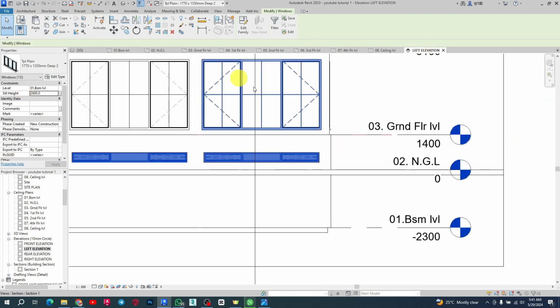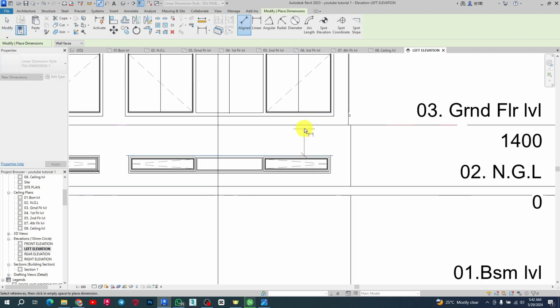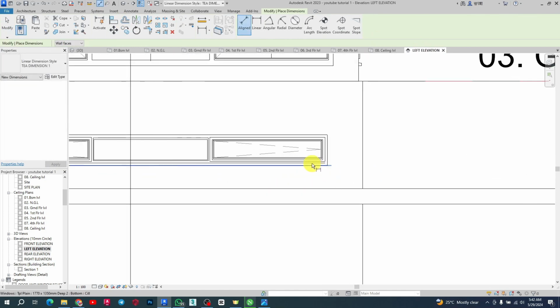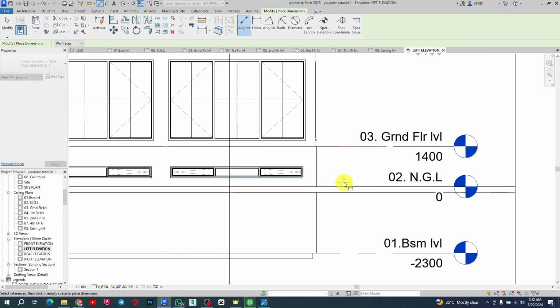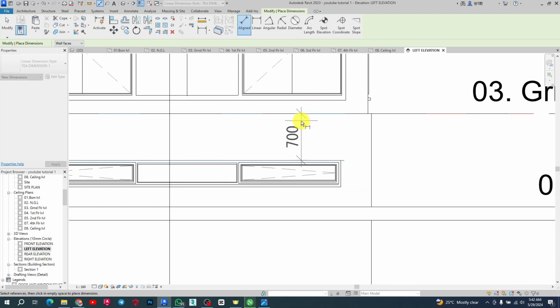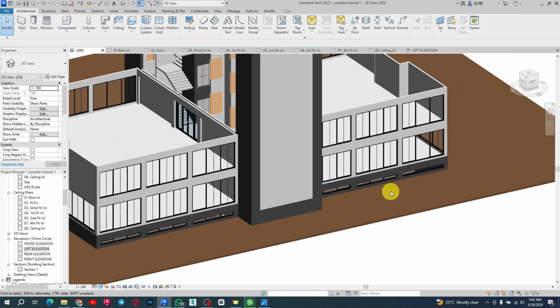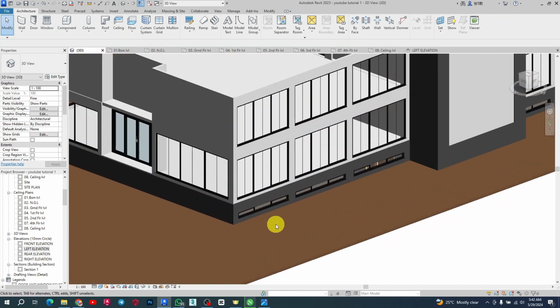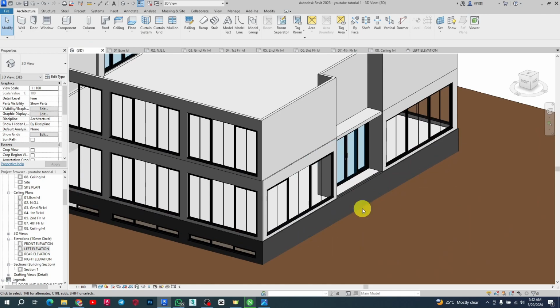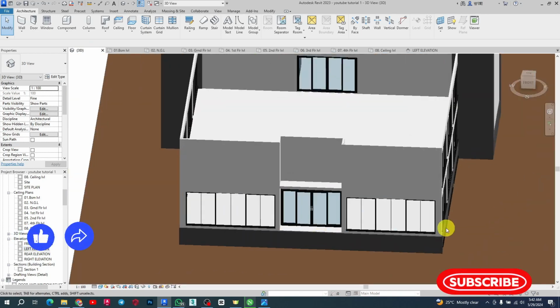So let's check this elevation again and see if we have that height. So from here to here is 700, and there'll be two courses of block down. I think it should be two courses, right? 1,400. This window is 40. Okay, so we should have from this level to this level, 700. Okay, that is fine. We have 300 from ground, from the natural ground level. So that is fine. We will not have it here because this is the entrance and there will be a staircase at this position before you get to that level.